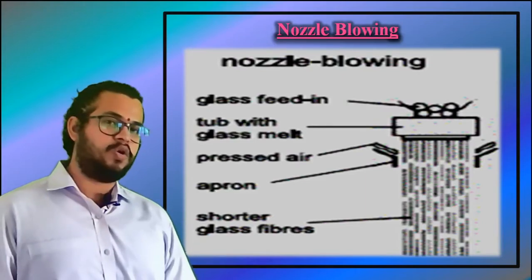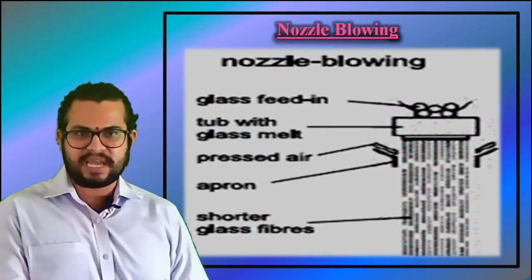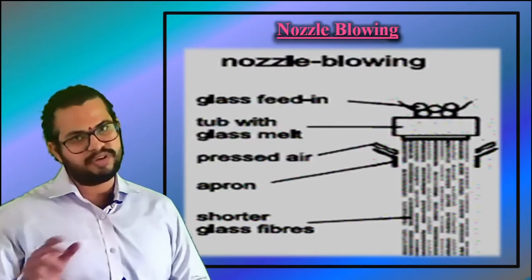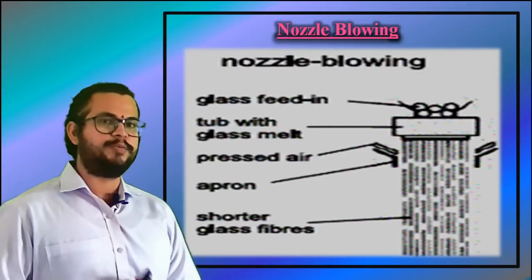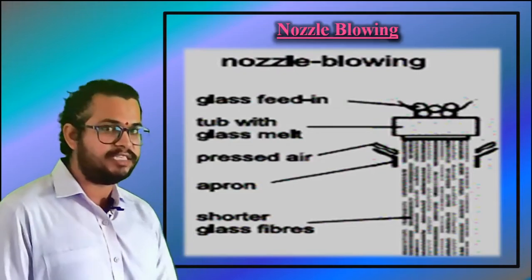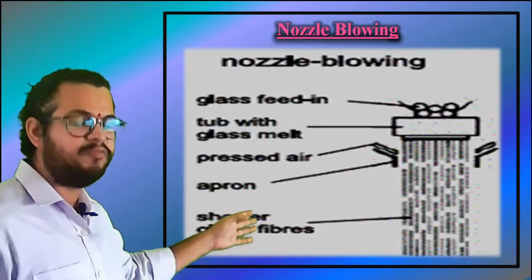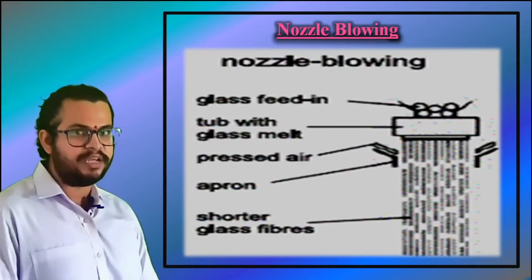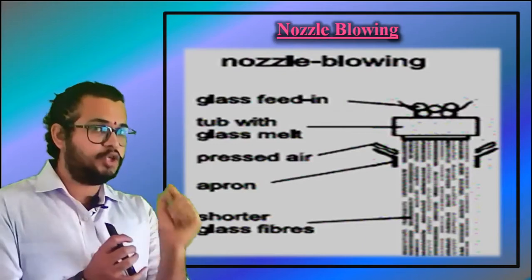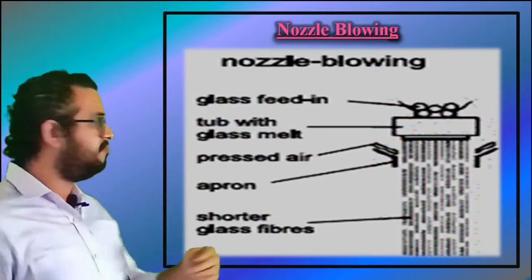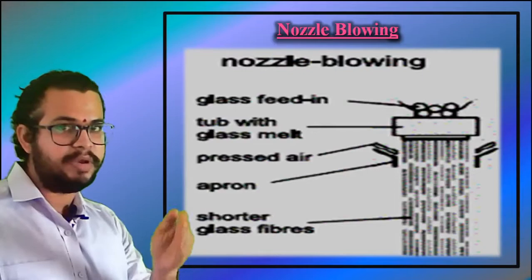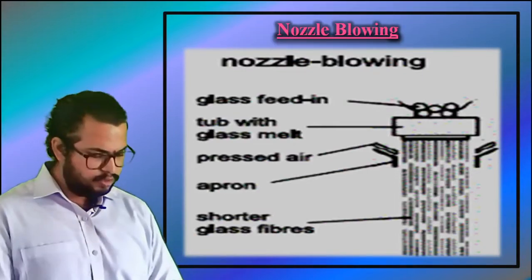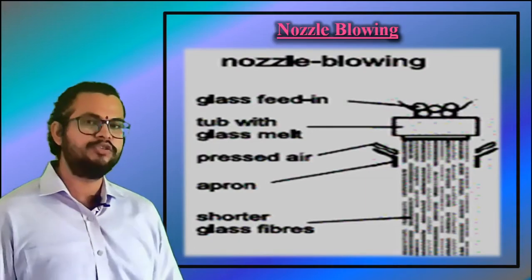A fluttering effect is caused by the flow of pressed air, which results in fibers of lengths from 50 mm to 300 mm. A lubricant is put on and the fibers are laid down on a sieve drum which sucks them in. The dry web received is held together by long fibers, with the short ones lying in between them as a filament material. Here you can observe long in between short. Then the slivers of glass fiber material are cut into required lengths and required shapes and so on.